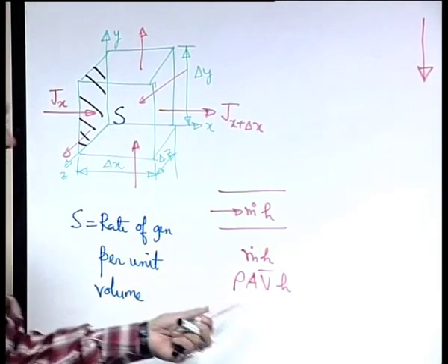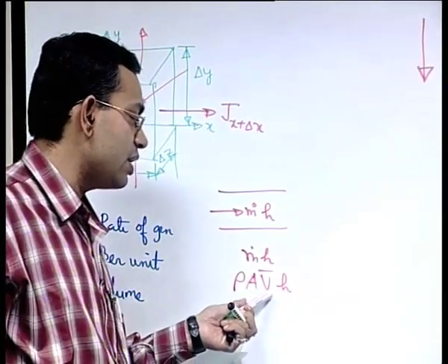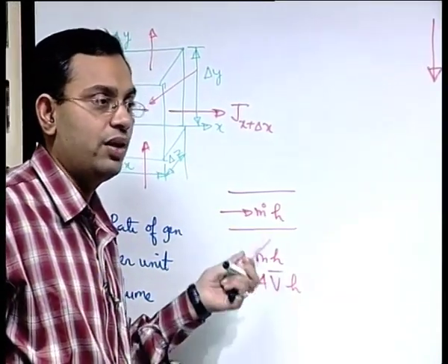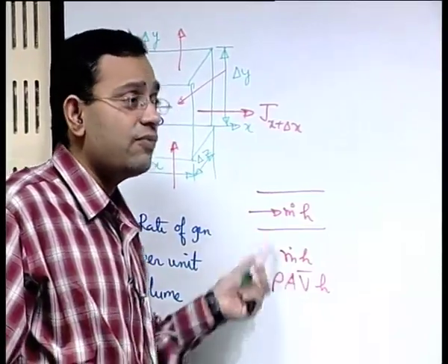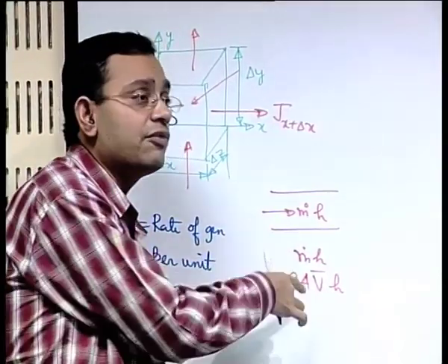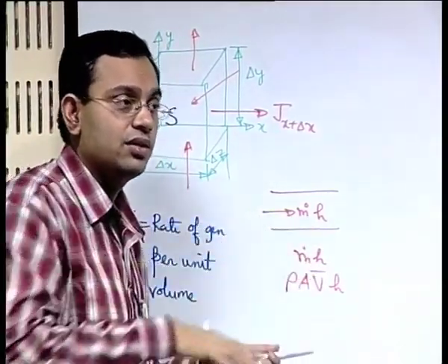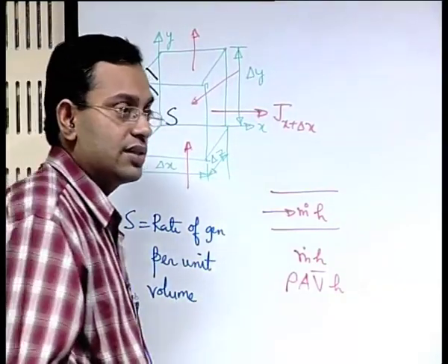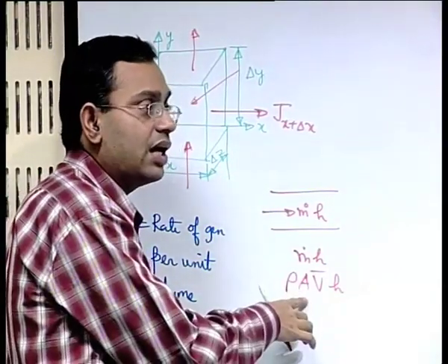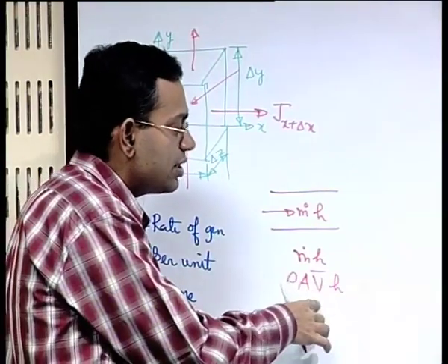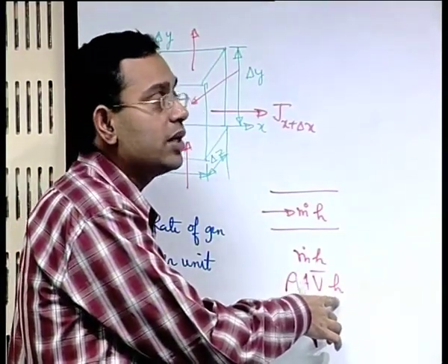If you consider it at a point, then instead of average velocity you replace it by local velocity. So what is the flux corresponding to this? Remember, this is advection, this is advection of heat. So what is the flux corresponding to this? Divided by the area. So rho into velocity into the variable per unit mass.